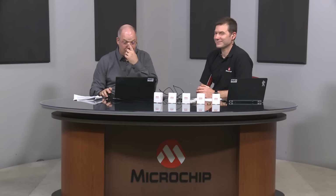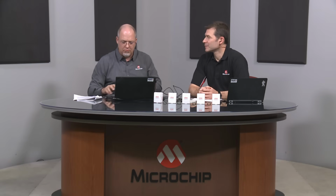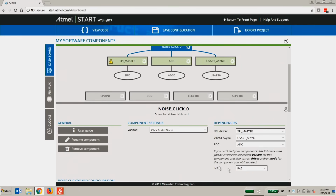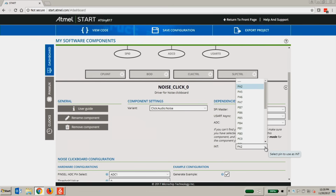So anyway, that's how we map the pins. Going back to the start here, you'll see one of the signals is int. And what happens is on the output of this click board, there's actually a comparator. When you surpass this threshold that we're going to define later, it's going to trigger a high on that pin. And that pin happens to be connected, thanks to the mapping that I did with that table, to our PA5 pin.